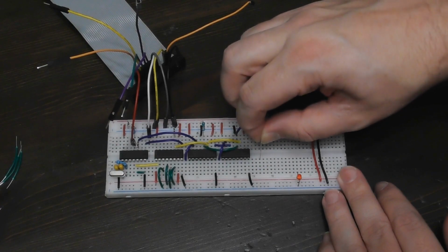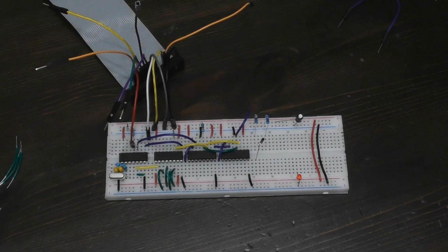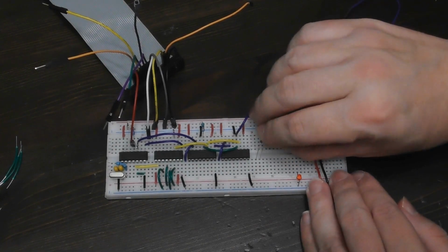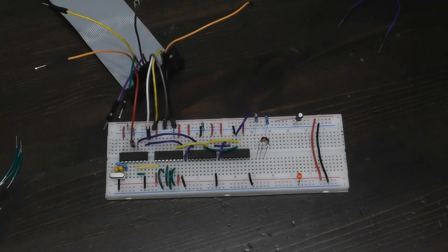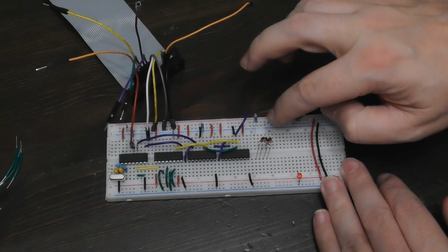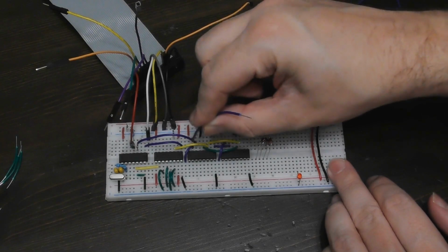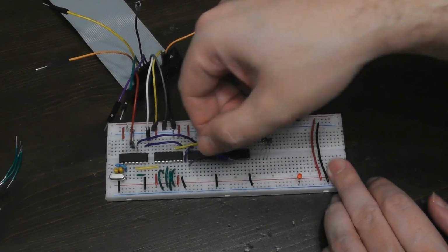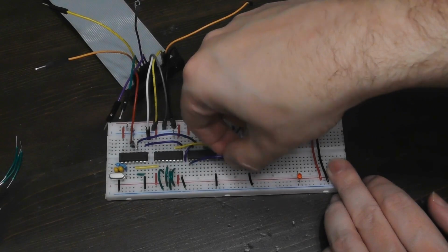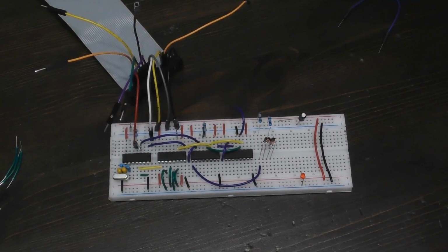I'm going to spread these diodes out quite a bit. So these are all pointing with the black band towards the top, and the top goes through that resistor to ground. So there's my 4 diodes and a pull down resistor, sorry. And I want clock pin 0. Clock signal 0 is actually the second pin of this shift register over here. So that's the first one I'm going to take. I'll put that down there so that you can see that.